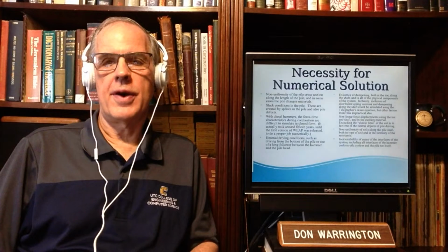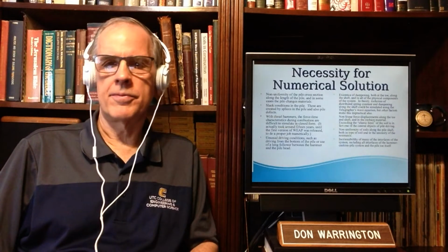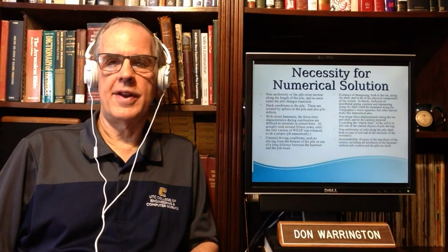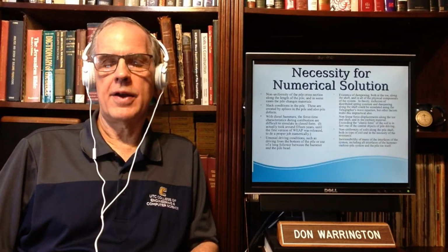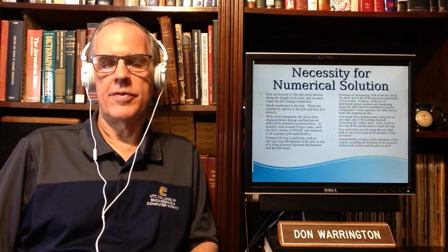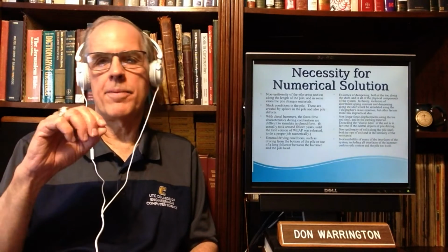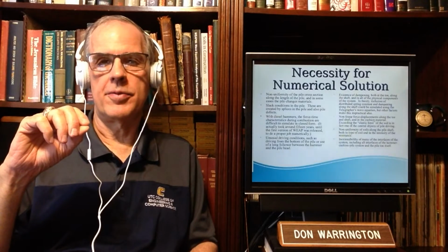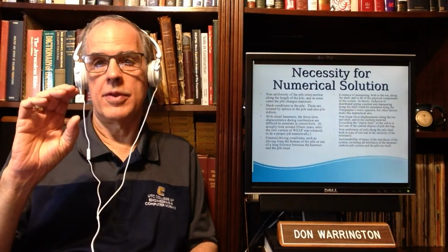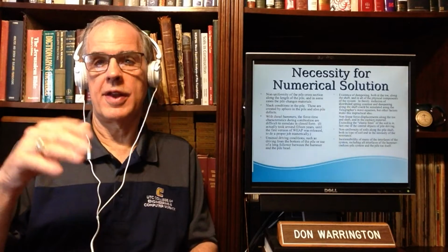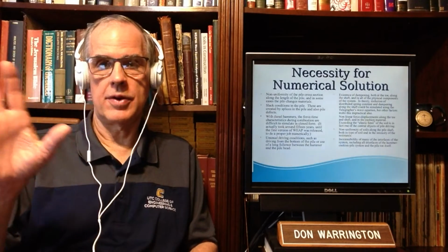I've gone into a lot of methods and I've kind of mentioned some of them in passing. Why the numerical solutions are necessary. The bottom line is that pile driving is a highly nonlinear phenomenon, and has a lot of nonlinearities, for example, inextensibility in the system. You have to model the system in such a way, for example, that the ram only puts the hammer cushion in compression. It cannot be in tension. It just can't be.